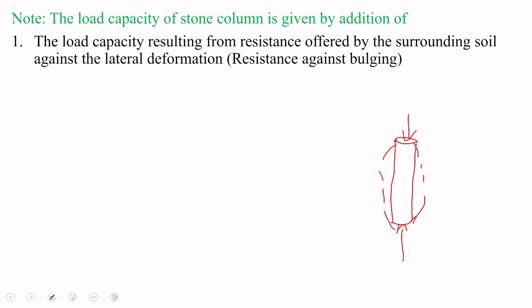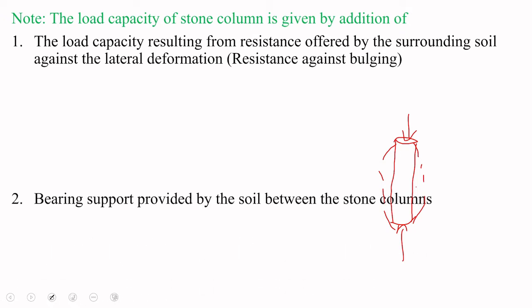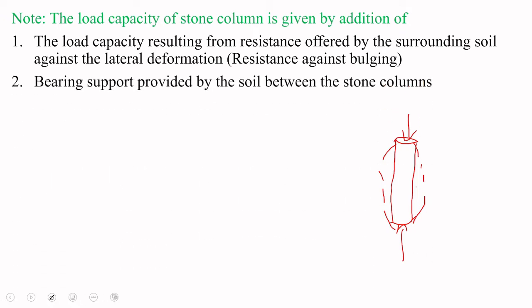So when it bulges, it penetrates inside that soil. The peripheral body where the soil is available will resist, and that force we will consider in our design. Second one is bearing support provided by the soil between the stone columns.